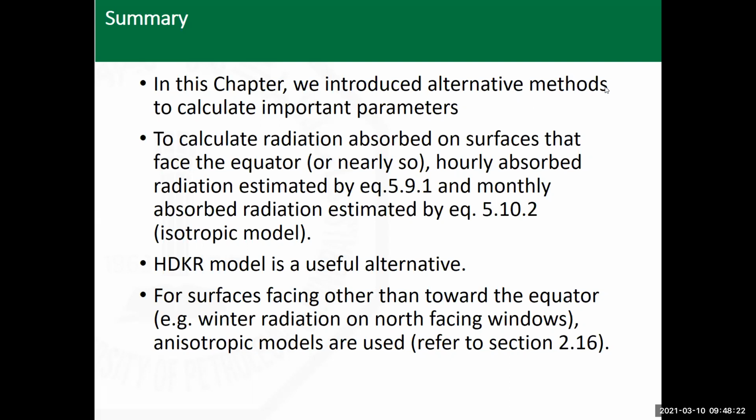Your answer that Abdurrahim mentioned, and most of you agreed with, is that the value of S is going to be higher for a single glazing. But we did not say why. Because the more glazing, the more energy will be absorbed by the glazing. That reduces the quantity that reaches the absorber surface, which means that less glazing results in higher absorbed radiation.